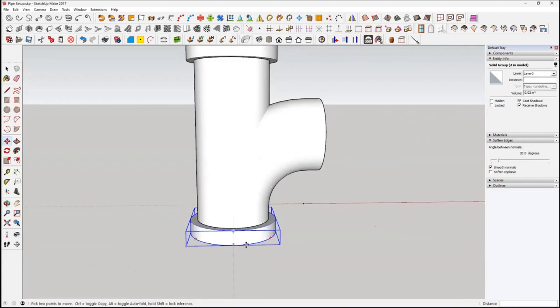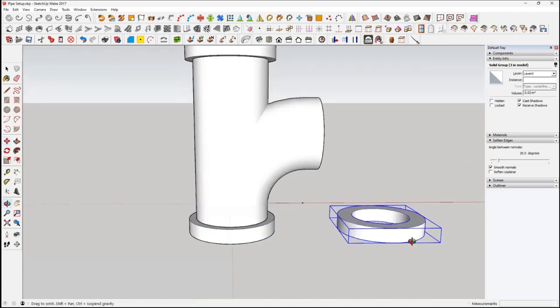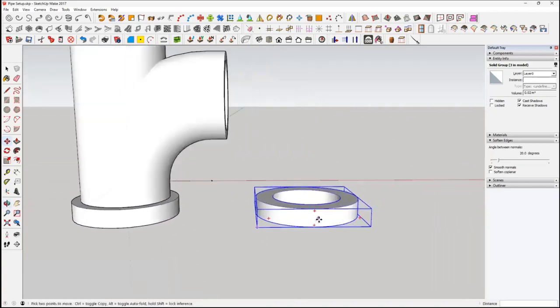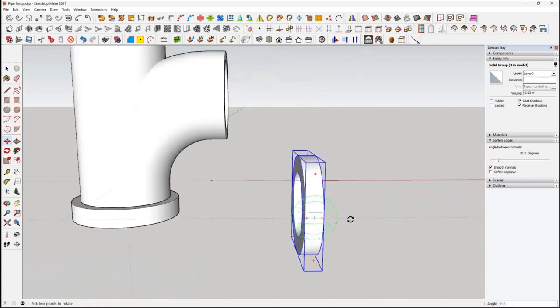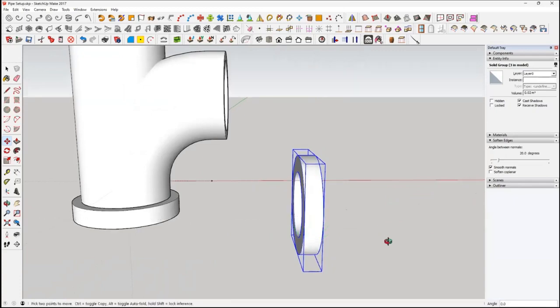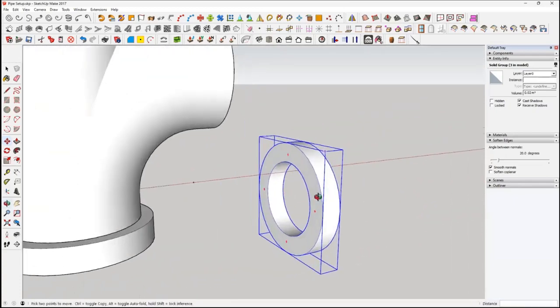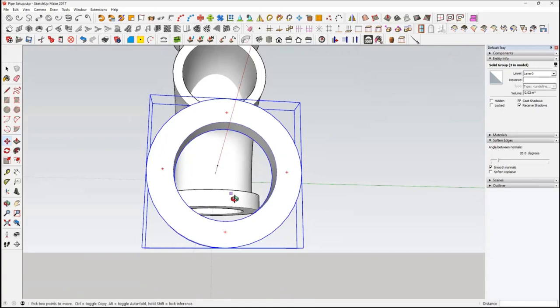So we want one on this end. Easy way to do it is control along the red axis. And do like I said before, if you hover over it, one of the crosses will bring up a protractor tool. Bring it round, angle 0, they'll be straight. Same again. See if we can get it spot on this time.